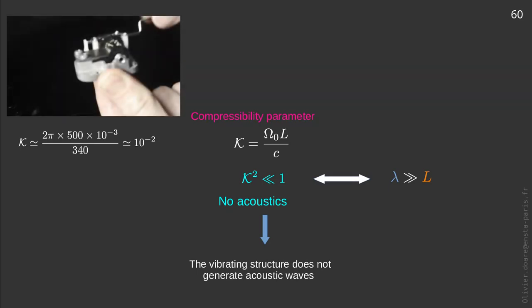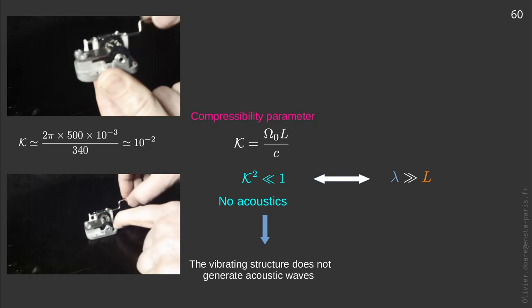On the other hand, if we couple the music box with a vibrating structure of larger size, we allow the characteristic length of the structure involved in the radiation to be much larger, say of the order of a decimeter. In this case, K is 100 times larger and the sound is much more perceptible. It should be noted that the vibration of the table is barely measurable, certainly of the order of a micron, whereas the blade has a displacement amplitude of the order of a millimeter. It is therefore the characteristic size L that comes into play in the dimensional analysis and not the vibration amplitude.